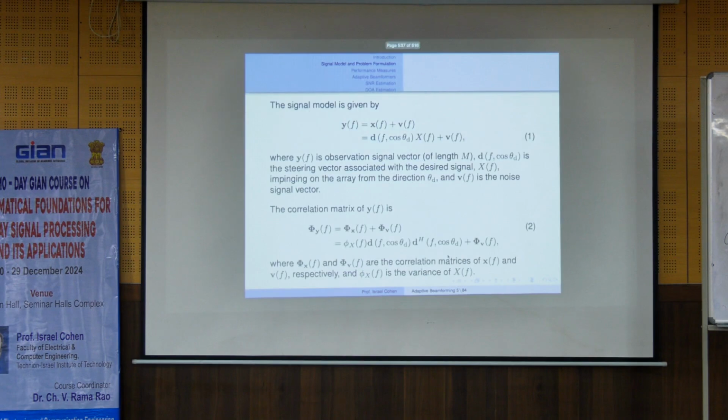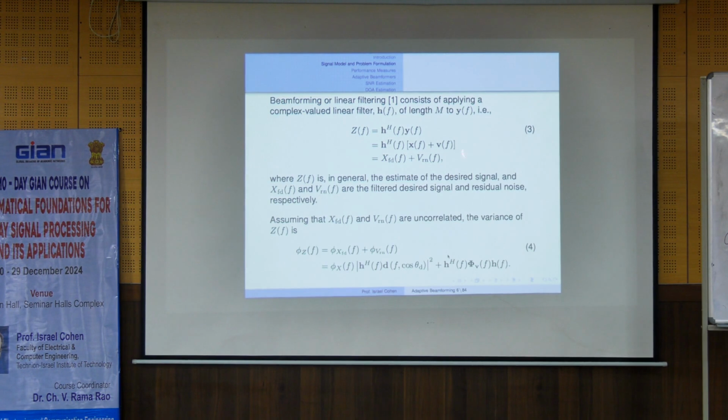This part is similar to multi-channel signal enhancement. So the model, you see, is similar to the multi-channel signal enhancement, but instead of a steering vector that is derived based on the relative transfer function, it's derived for a free field environment. No reflections, only direction. And we can define it here. Once this is the variance, the beamformer is the same as a filter. This is the beamformer.